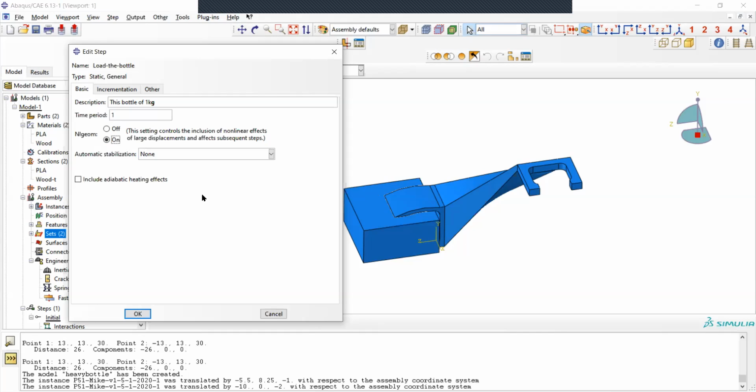So that is fine. In case you have friction, and in this case you do have friction, it is advised to have some dissipation, some energy absorption, to stabilize the displacement. So it's good to add at least a bit of either dissipated energy fraction or damping factor. They are more or less similar. You can leave it at default and add a bit of energy dissipation. If you're familiar with simulation, you need some stabilization effect, and that's why you need this energy dissipation.